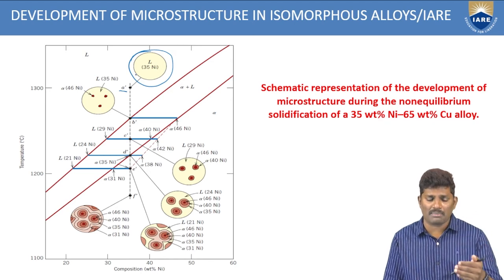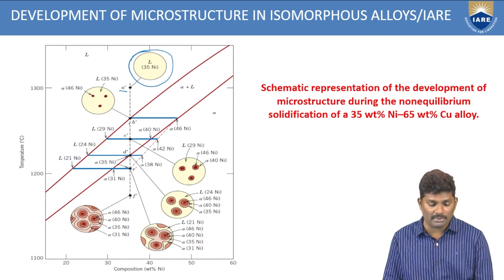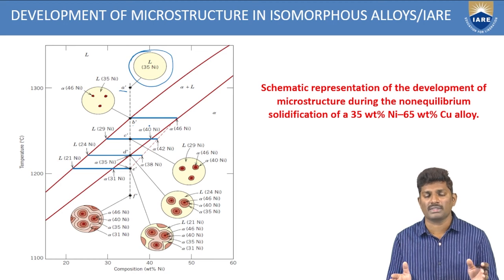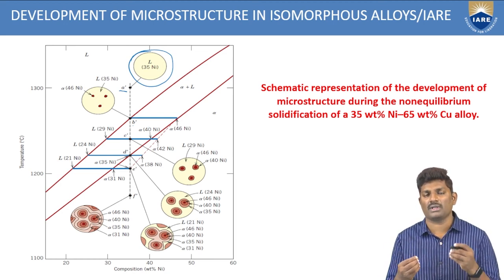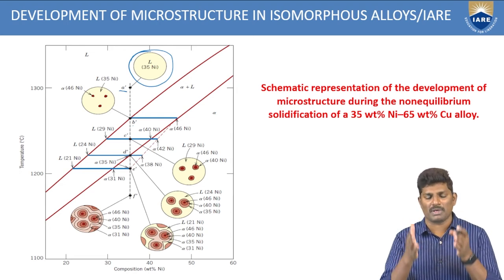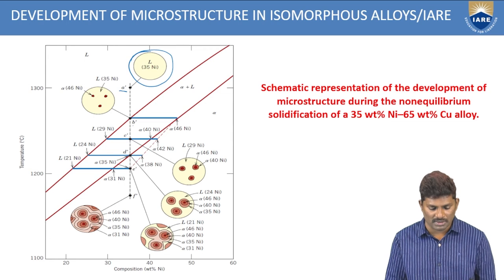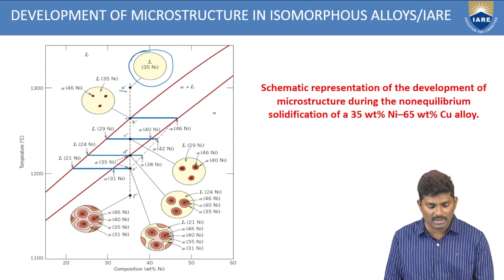Now, if you reduce the temperature, it comes to point B dash. This is B dash with rapid cooling. Again, it is falling under the 2 phases, so you have to draw the tie line. From the tie line, you find the intersections of the 2 phases, and from the intersections, you drop the perpendiculars to find the composition. Since point B is lying between the 2 phases, I am drawing a tie line here, which has the 2 intersections.